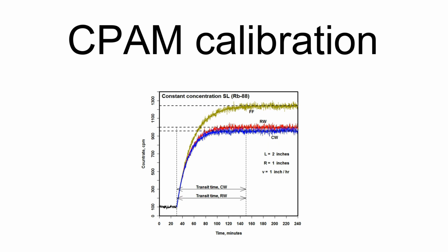the selected quantitative method. What is of interest for the MDC is the variability, not the level, of the CPAM background count rate. This variability is measured using the standard deviation. Care must be taken to account for bias in this estimate due to the autocorrelation of the sequential monitor readings. The autocorrelation bias can make the calculated MDC significantly smaller than is actually the case, which in turn makes the monitor appear to be capable of reliably detecting smaller concentrations than it in fact can.